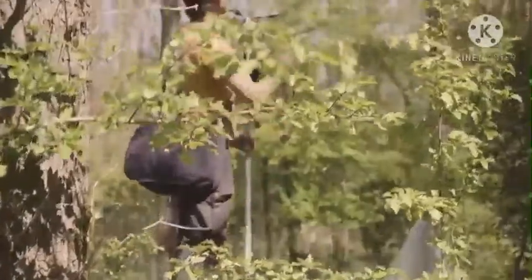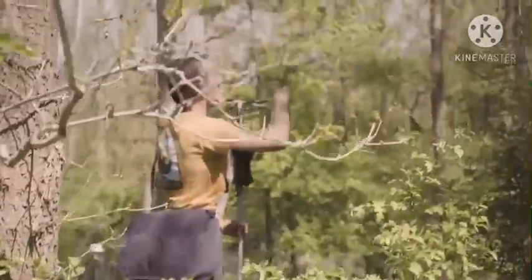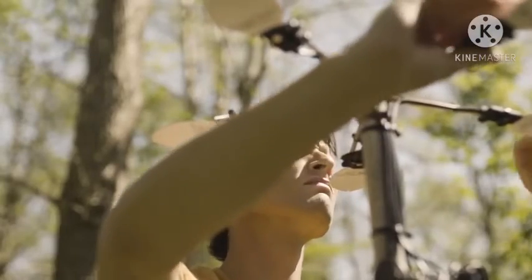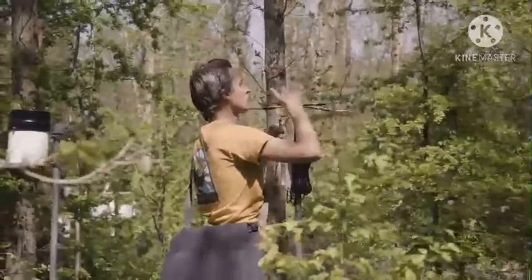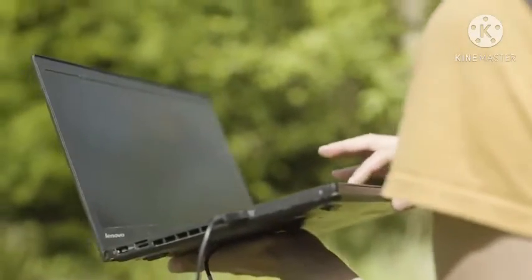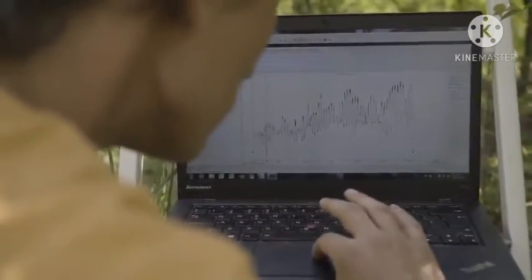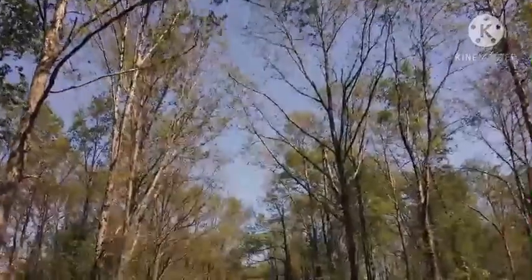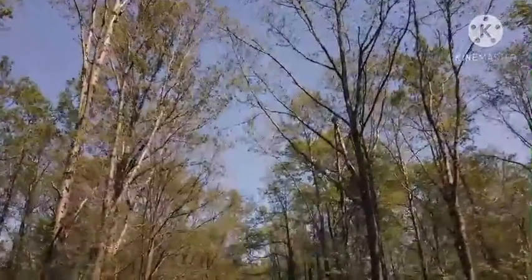Another interesting instrument we're using are actually artificial leaves. Artificial leaves are able to measure how wet they are, and that's important to understand when we have a rain event happening in the forest. They can measure how fast the canopy gets wet. By having these measurements and the rain gauges, we can relate the intensity of the rain, how much it rains per hour for example, to how fast the canopy is re-wetted.